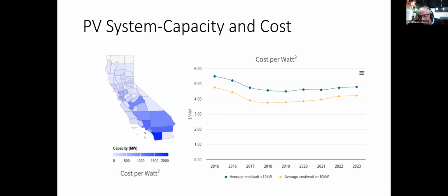Yeah, but I think that within a few years, because of the domestic production, the availability will be much more, and also the cost will come down. Solar used to be like $11 to $14 per watt installed. Now it is about $4 to $5 per watt installed. If you look at this, the average cost is somewhere around $4.2 per watt installed. With the incentives that the state and federal governments are providing, the cost has come down quite a bit.